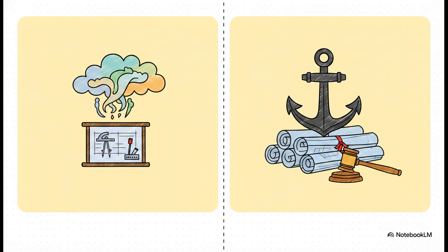On the flip side, anchored firmly to reality is the architect of record, or the AOR. This is your technical anchor. The AOR takes on the full legal responsibility, the standard of care for the safety and compliance of the construction documents. They're locally licensed, they physically sign and seal the drawings for permitting, and they're basically the glue that integrates the structural and MEP engineers. Appointing a clear single AOR is literally your first line of defense.